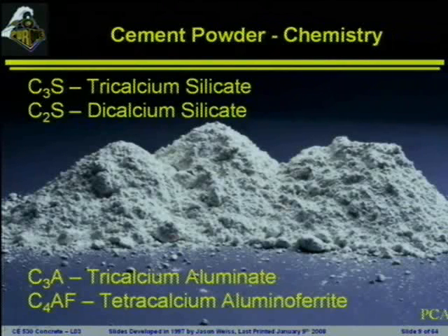As I mentioned before, what we're really interested in are the calcium silicates, which are going to make up about 75% of the system. And then we're going to spend a little bit more time talking about the aluminate phase. One of the things that you will notice is every time we start to talk about these percentages, and I put the percentages up on the screen, they aren't going to total up to 100%, because there are